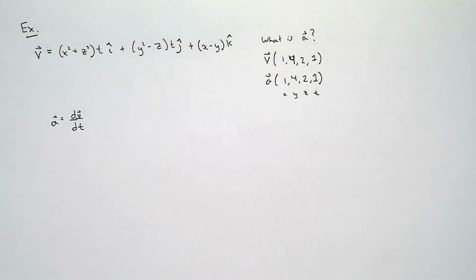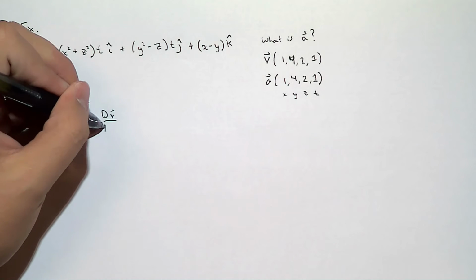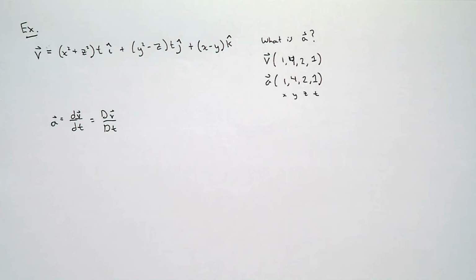But, of course, our velocity doesn't just change with respect to time, it changes with respect to space. So we want an expression of acceleration that can account for the acceleration of any fluid particle within that body in whatever position it is. So how can we find that acceleration? We use the equation we had before, where we take the partials with respect to x, y, and z. That's correct, right? We find the material derivative of velocity with respect to time.